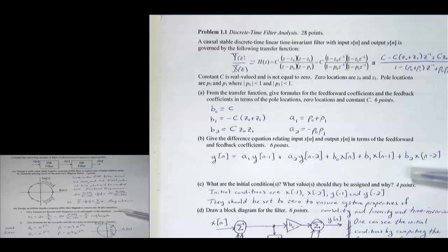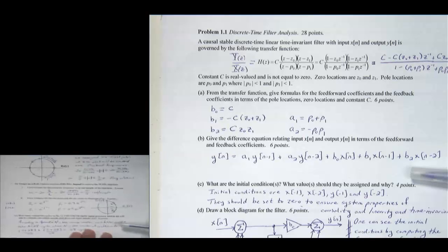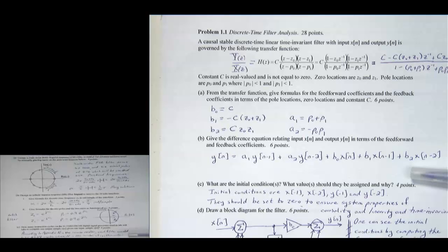This is a really common problem, having this kind of interferer. Anyway, this particular interferer is at 50 kilohertz, so where does it reside in discrete time? With a sampling rate of 400, we know how to do that. It's 2 pi f naught over fs. This gives us ultimately pi over 4 radians per sample, the 45-degree point. You don't have to draw the pole zero diagram. I just do it here for illustration.